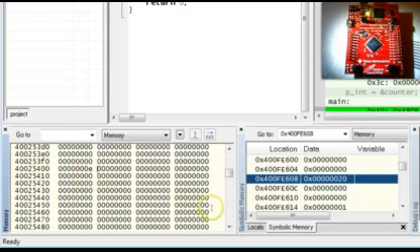Additionally, to set the function of the pins as digital output, scroll further down within the GPIO F address block to the address 4002551C and again set the bits 1, 2 and 3 to 1. So finally, you can try to control the LED. You do this through the GPIO F data register located at hex 400253FC.